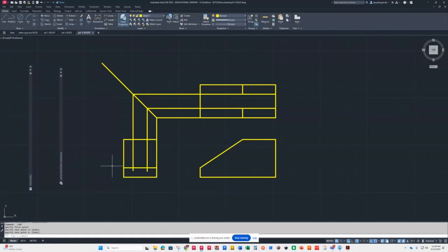It's actually at 0.75 from the bottom. So if I go to offset, put in 0.75, then I can draw this line up here like so. And then I can go back and trim out some things.